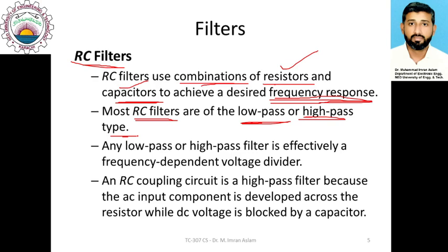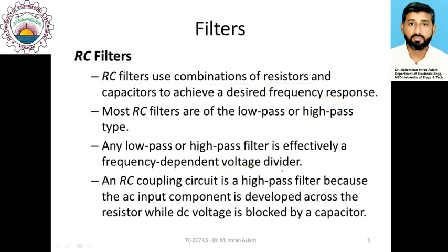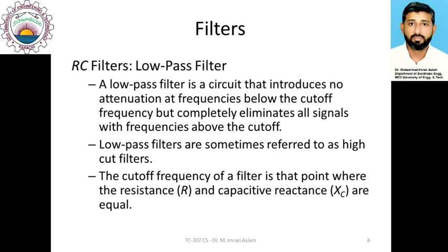Practically, those RC filters behave like a frequency dependent voltage divider, and the voltage dividing function provides the specific response, whether it is a low pass or high pass filter, depending on where we observe the output of the system. Let me show you different types of filters. First we illustrate the RC low pass filter.